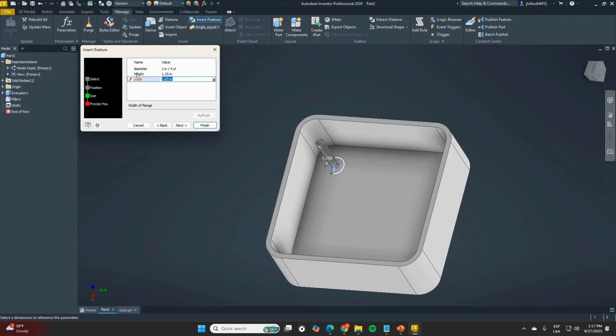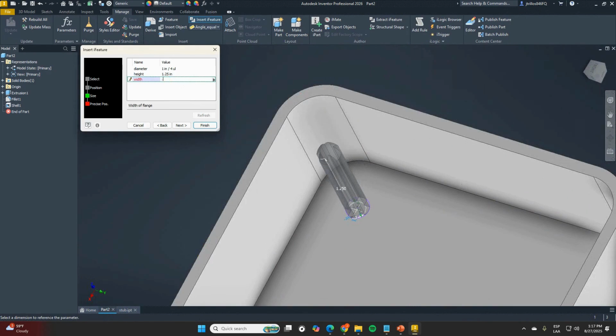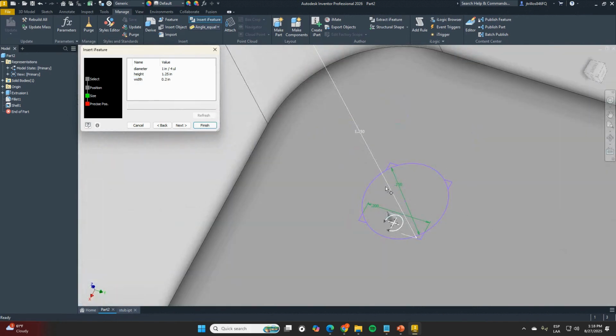All right? Same for the width. If I specify the width to be 0.1, that's going to pop up like this. Okay? If I specify something very, very small, same kind of deal. I cannot use it. All right? And even if you try to use parameters that may be in your range, right? But that would render a wrong result, the iFeature is going to give you a warning. So, for example, if I specify a width of 0.2 or something like that, okay, basically that's not going to work because the width is just too big. All right.